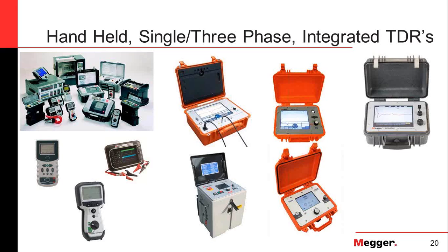So you can have an electrical tree, which is what a fault is, if you will. It's where the insulation's completely broken down. The TDR can't see that by itself. You have to create that arc. We do have test and diagnostics methods that can tell us how severely damaged the insulation is. That would be, probably, the tan delta test.